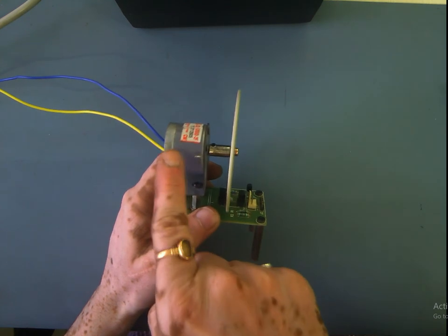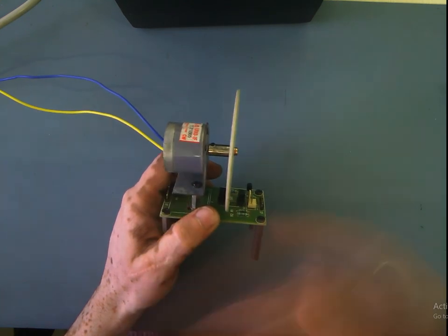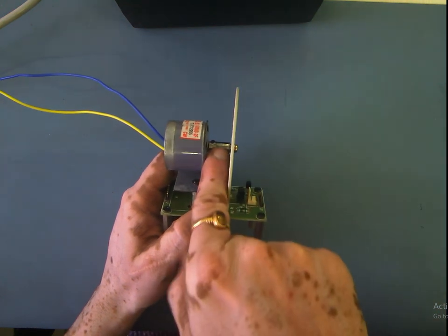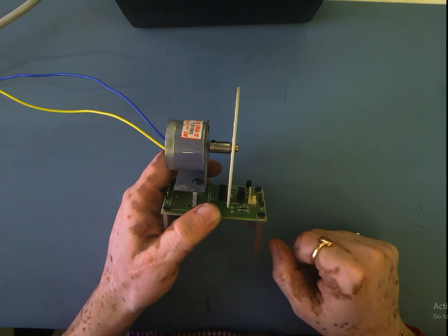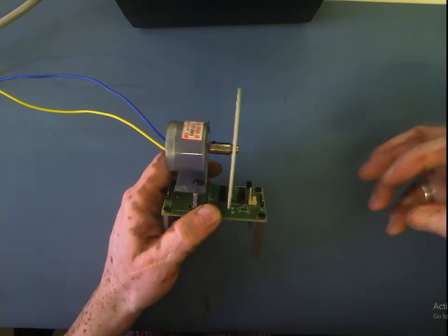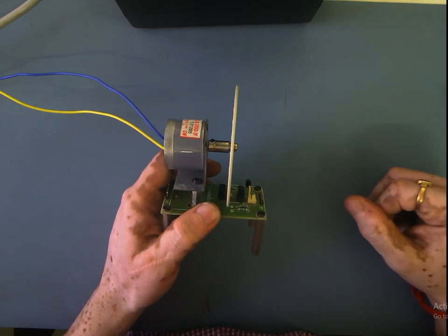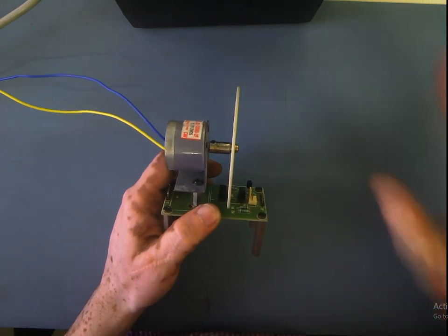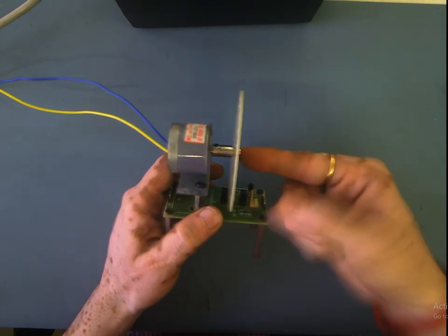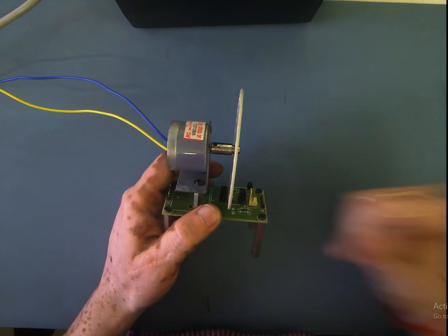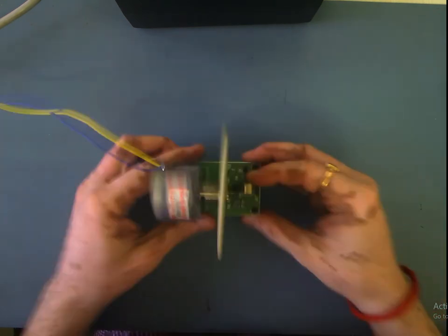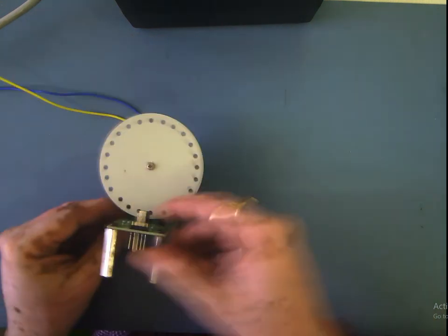This motor is actually fed by the signal for its rotation, and that motor is rotating since there is a mechanical coupling between this motor and that motor. So from the terminals of the second motor, we will be taking out the voltage. You can simply see the voltage is directly proportional to the speed of this shaft, because the faster the motor rotates, the more voltage will be induced. So this is another method, the tacho method, but here we will be using this one.